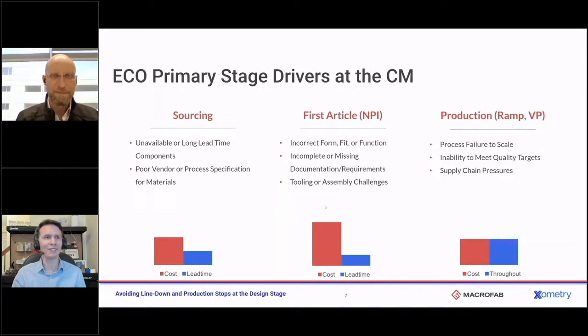So this is all about the preventative stage. To that note, when you have an ECO, there are some things that we call grooming in production, which I think are the freebies. We understand we need to shave it off here to get a couple thou if needed. But there are other things where it's like I'm missing a hole, or this does not mate to my particular part, and that's price. So in our world, it's always about what am I going to modify?